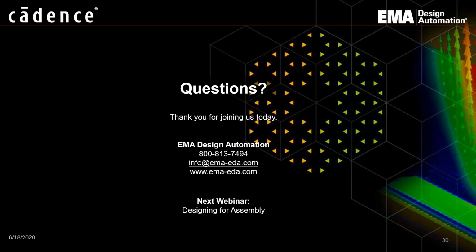And the solid parts, say you have a package or a board, as I said, we can read in the SPI file, MCM file, board files, SIP file. Then we can create that 2D layered structure or 3D like I just showed. Then we can use those imported solid models to create a CFD model. That CFD model could be as detailed as the solid model, or we can have an equivalent or simplified model. It depends on the model size.